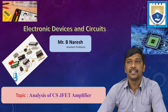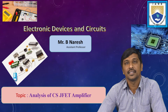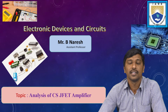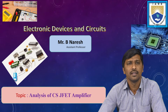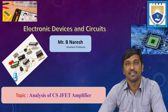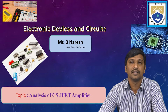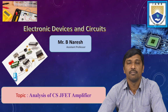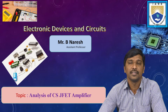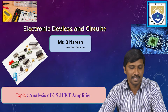In the last two sessions, we discussed the FET construction as well as the characteristics in the JFET configuration as well as the MOSFET configuration. The major application of the FET is as an amplifier. For this amplifier, we also discussed how we can maintain the proper operating point by applying biasing voltages between the gate and the source as well as the drain and the source.